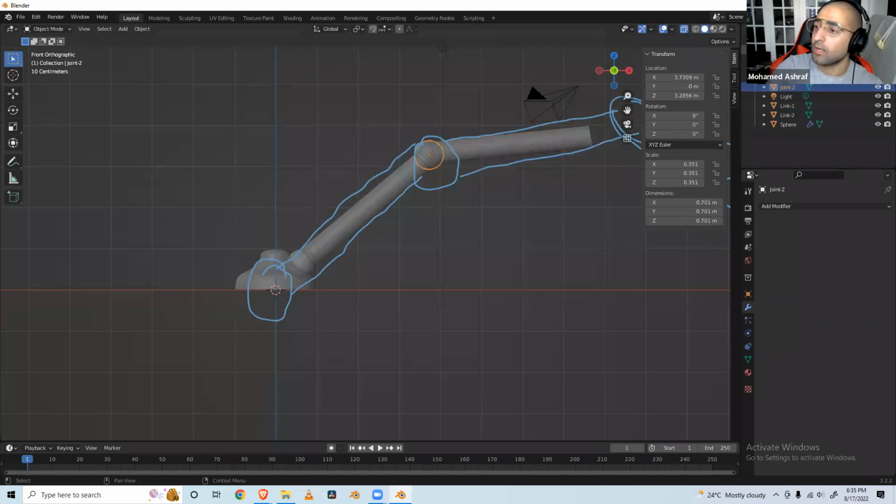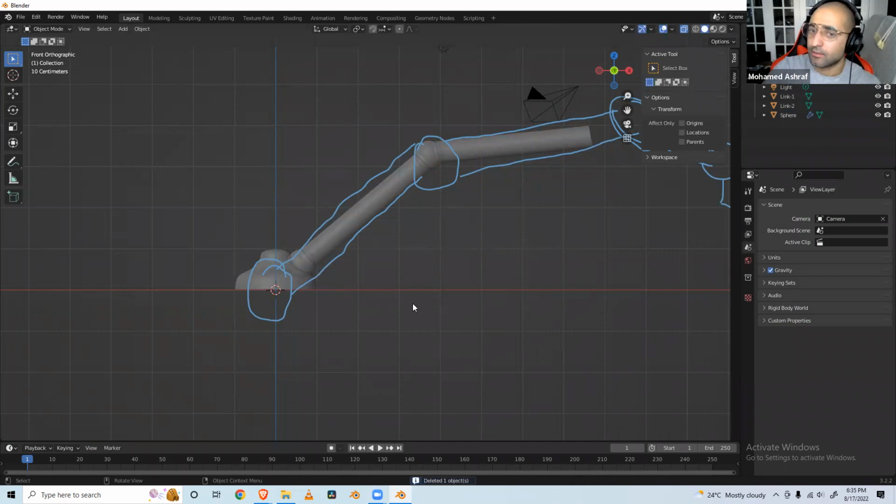Now, one really great thing about this view is that it allows you to look at potential duplicates, like the one we have right here. If I click on joint 1 and joint 2, you can tell that there's an overlap. And if I press G, yep, this is a loose duplicate that we don't need. I just deleted it, and it's something to really take care of because it can come back and bite you moving forward. If you're animating, if you're rigging, if you're keyframing, this is something you need to really be aware of in the future.